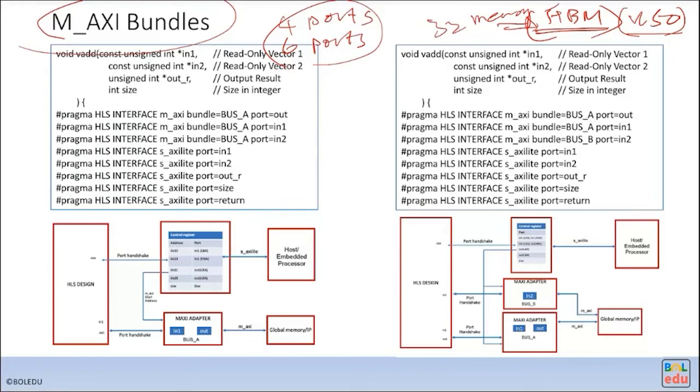If you want to design a high performance system, you want to fully utilize those memory channels. Especially for AI applications, we all know that the performance bottleneck is the memory throughput. So definitely you want to fully utilize the memory channels. In that case, I can assign those variables to different channels, which gives you a higher throughput.